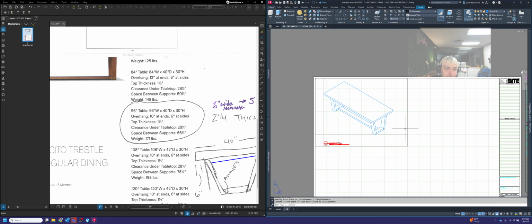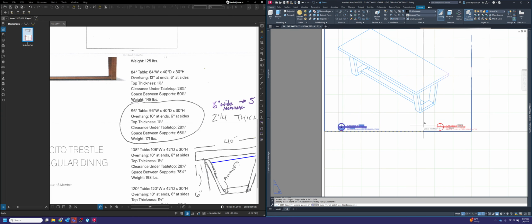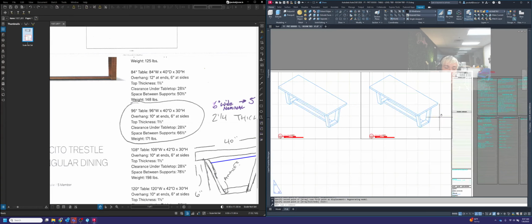Because if you remember, when you're plotting a drawing, you want to go top to bottom and left to right, just like you were reading a book. And your views do need to be in a very specific order, aside from detail views. We're always going to go axonometric, plan, RCP, if it applies, and then elevation, section, and then again, just to recap, details are anywhere they can fit.